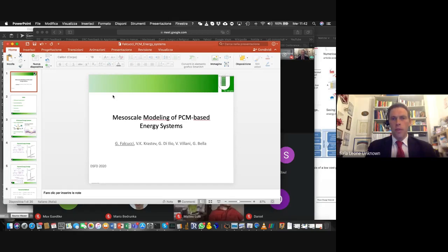And this is quite good for us, both from a simulation point of view, which is precious, but also from an implementation point of view, because you can deal with these systems without having the issue of considering the increase in specific volume, which otherwise you must consider in a liquid to vapor phase transition, which is dramatic. So this is quite good, and this little difference is just reabsorbed by our lattice Boltzmann implementation.